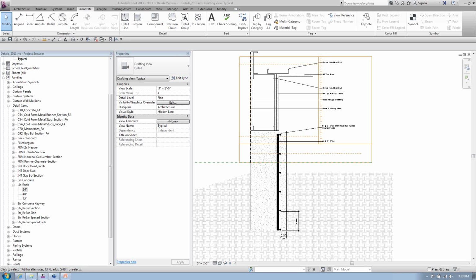There are workarounds to that. If you take the tag and build a very long line in there, so no matter if there was 1 line of text or 3 lines of text, it was always going to the same location. That does work. The problem is then when you hover your mouse up here, you're grabbing that tag, which is way the heck down there. So there are workarounds to it. I know that's a graphics issue, but this is not a liability issue. And I personally don't think it's worth the frustration and time to change it. If we ever get the option to have top, left, right, bottom, whatever from Autodesk, great. But until then, I really don't stress about it.